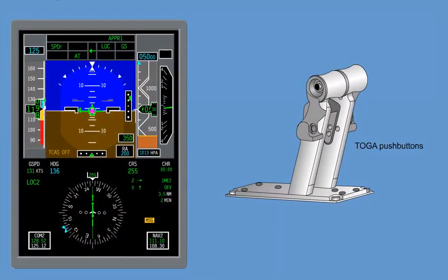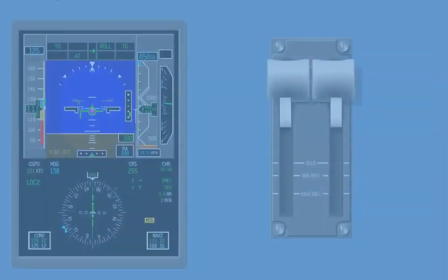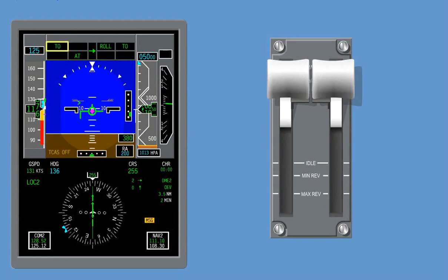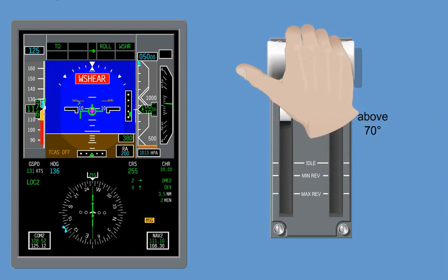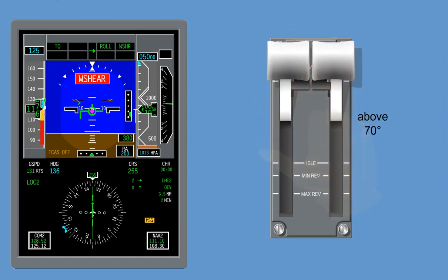This mode is a flight director mode, and it is engaged either manually by pressing the go-around button while a wind shear condition is detected, or automatically by operating in go-around or take-off mode, or when thrust lever's position is above 70 degrees and a wind shear condition is detected. In this condition, all the other flight director modes are cancelled, and the altitude pre-select, go-around, and take-off modes are inhibited while in a caution or warning wind shear condition. No lateral mode is inhibited while in wind shear mode.